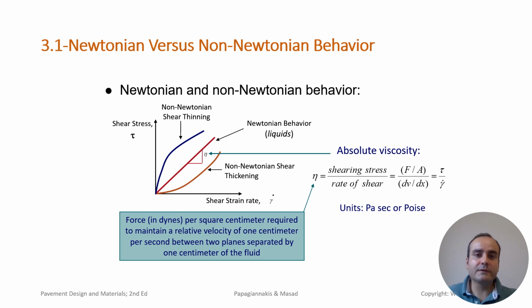Asphalt behaves differently at different temperatures. At high temperatures, the viscosity decreases, meaning the asphalt becomes softer and more fluid. Conversely, at low temperatures, the viscosity increases, making the asphalt harder and more prone to cracking. For pavement design, this relationship between temperature and viscosity is important.